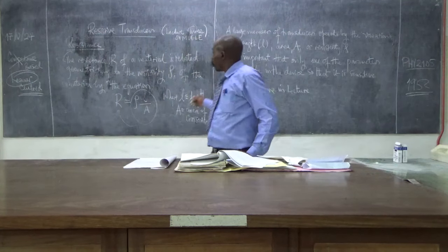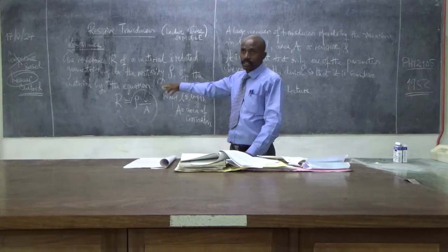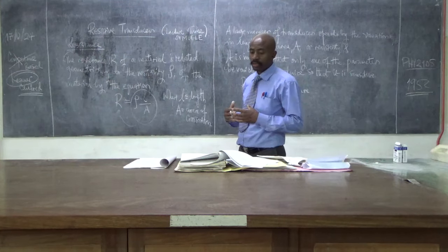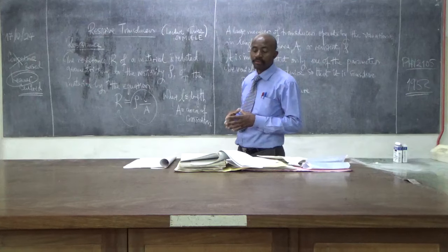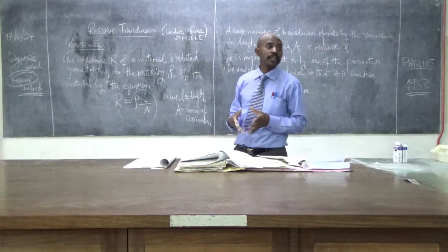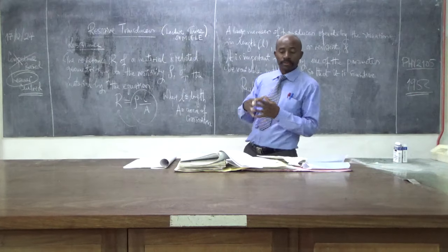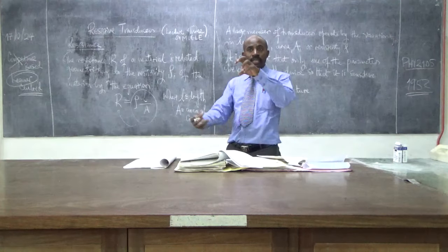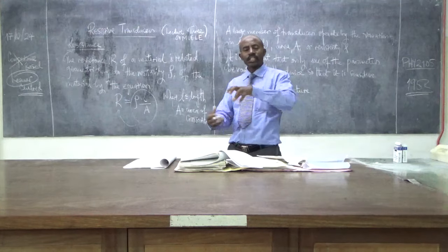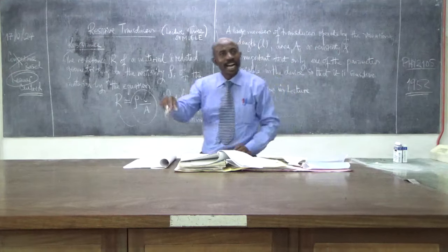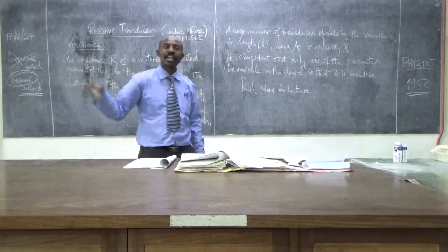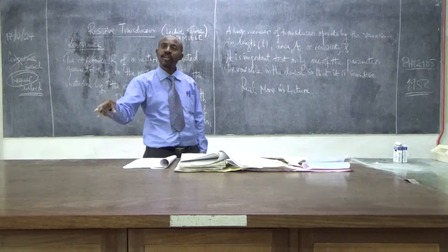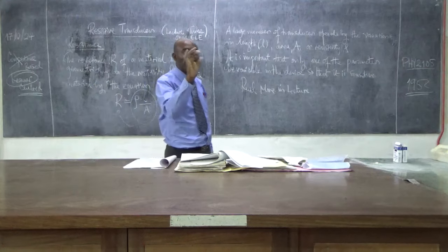So, this was about resistance. So how about the inductance? If you have a coil, first of all, the simplest sensor is the transformer. You have your primary having an AC, that AC producing a changing field, and that changing field gives you a voltage in the secondary. It induces a current in the secondary coil, and the secondary coil gives you a voltage.